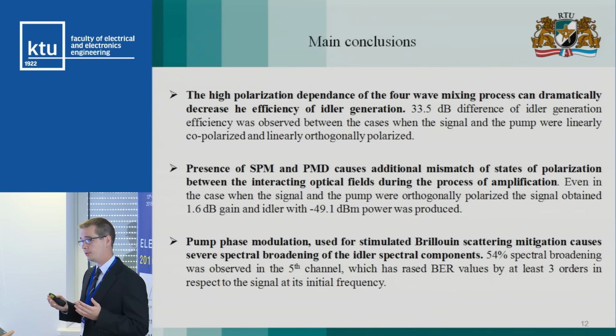So in systems where idler spectral components are used for all optical signal processing, while choosing the frequency tones for modulating the phase of the pumping radiation, one must not only take into account the achievable level of amplification, but also needs to control the idler spectral broadening. Otherwise, we might just lose quality from the signal.